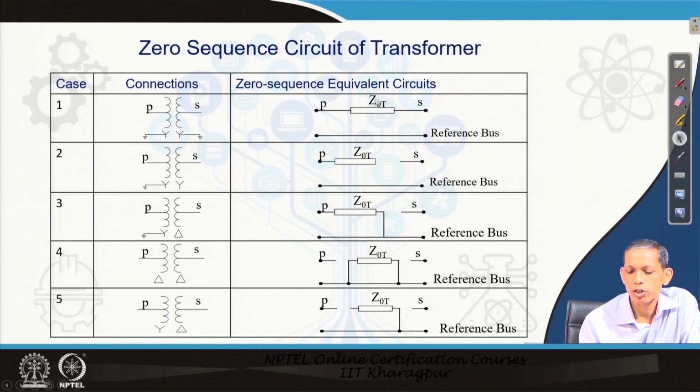So, therefore, the corresponding zero sequence impedance is connected to the line side in both perspectives. When it happens to be an ungrounded star, then it does not find a path to the ground. Therefore, the zero sequence current does not flow in the line, and the right hand side in this case is no more connected to the system.